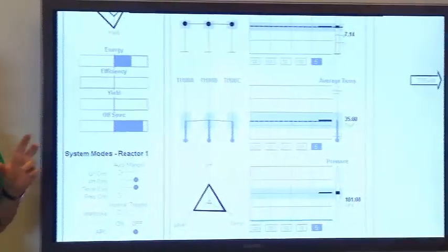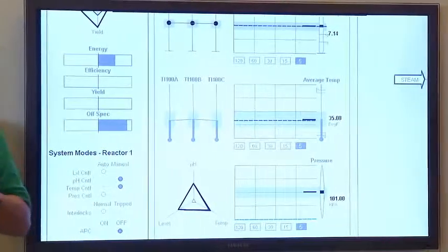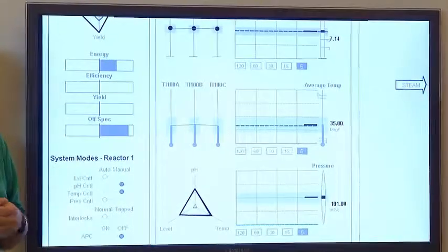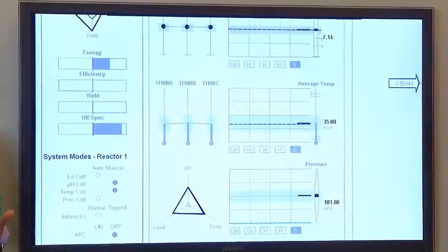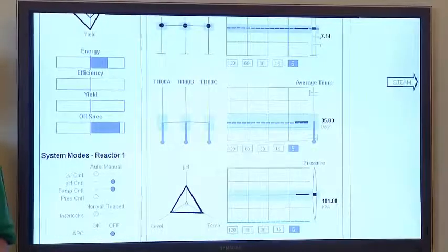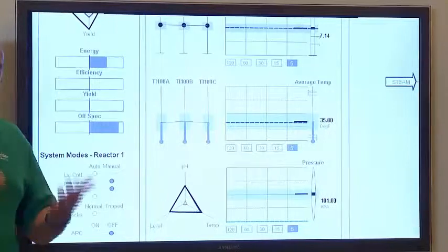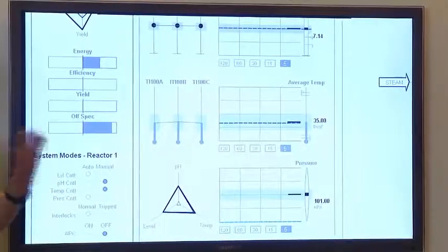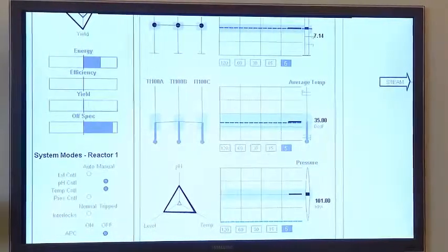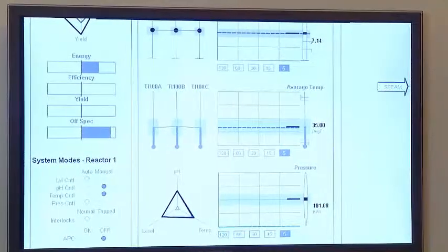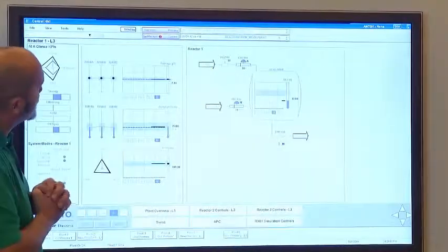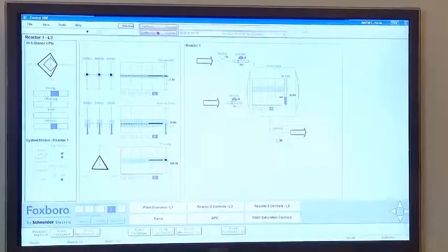So around the topic of alarm optimization, it's better that operators are given enough visual prompts to stay away from alarms or alarm limits as opposed to exceeding those thresholds and creating an alarm shower of some description.